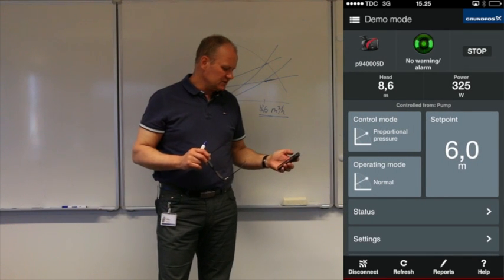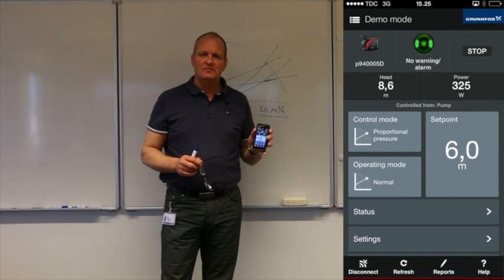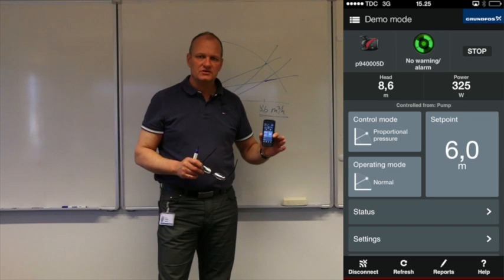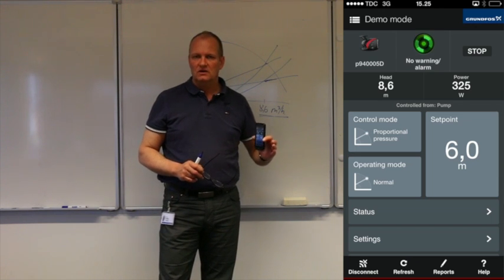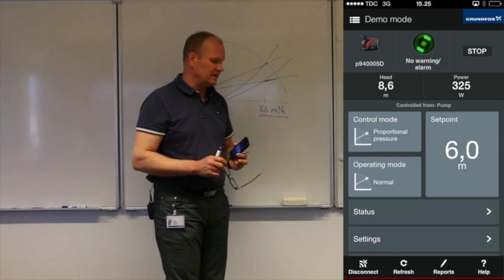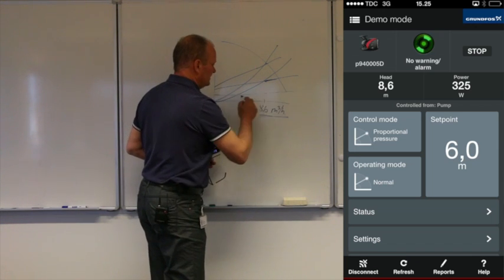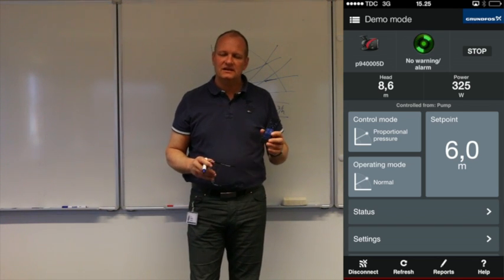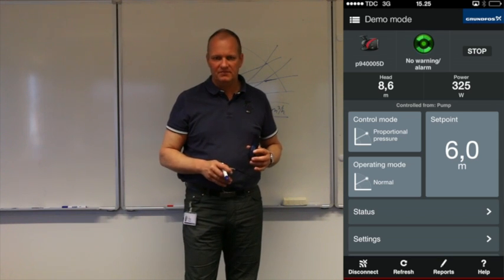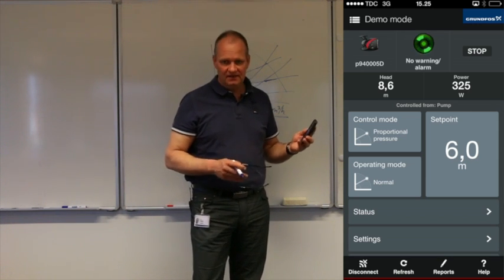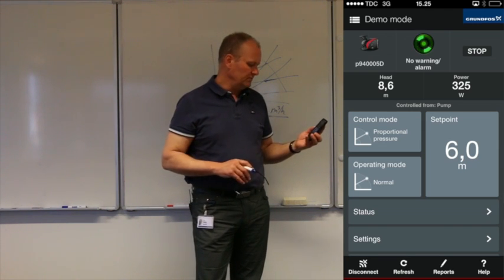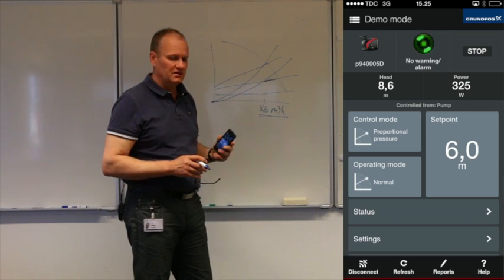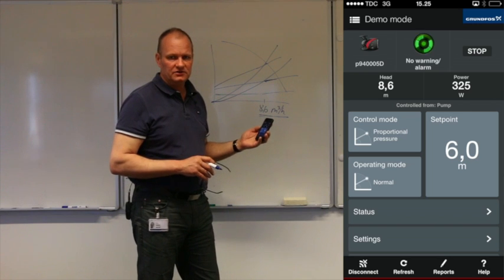So I would say that trying to play a little bit with your Grundfos Go, pushing the set point downwards until you see that the flow is now dropping, then you would know that you have reached maybe the lowest possible set point for your pump. But it requires a little bit of patience, and you need to play maybe half an hour or so. But then once the set point is set, then you will know that you have reached the lowest possible energy consumption for your pump.